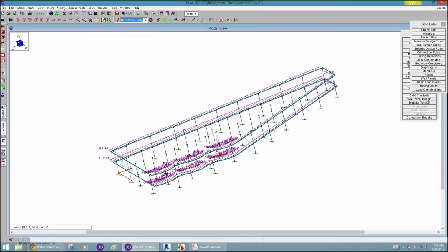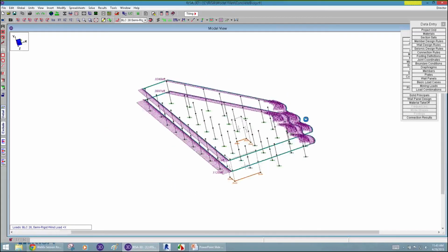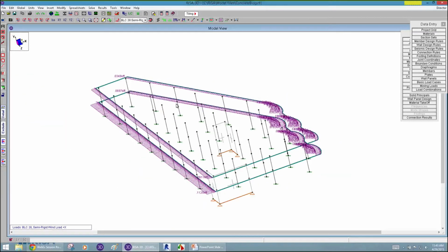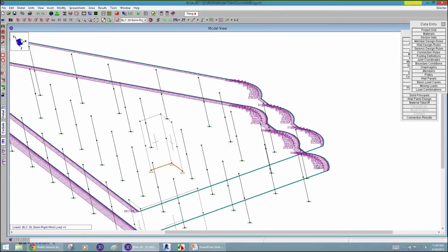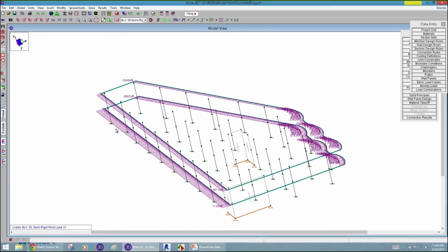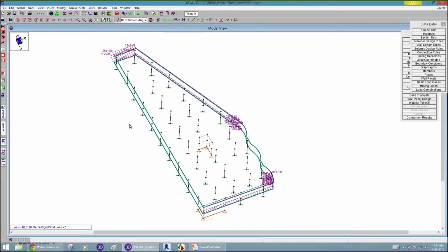And we see here on each floor level, you're seeing the windward and the leeward forces. What's nice is that curved element there, where we said it was a little change, it's not quite directly on per point when we did it ourselves manually, it's all calculated for us. So whatever needs to be on that distributed edge there is put on there for us and calculated for the windward and leeward directions. And we can see that in the Z direction as well. So Z is pretty easy there, but we do have this long diagonal edge where we'd have to calculate that on that projection. So it's a little harder, but it's all done for you automatically.